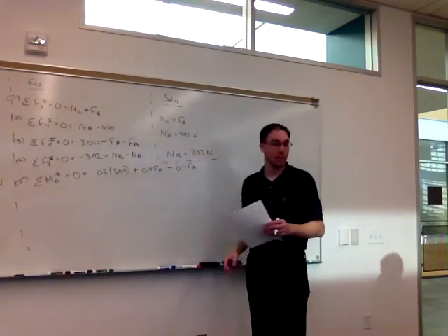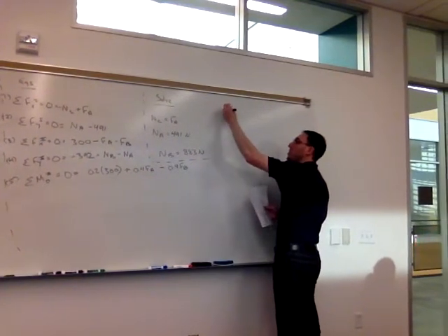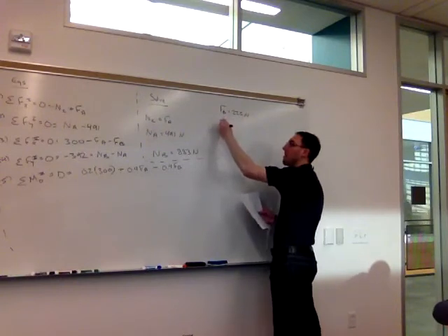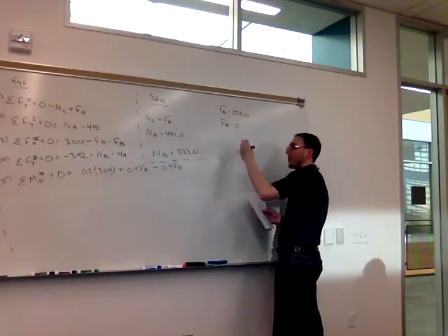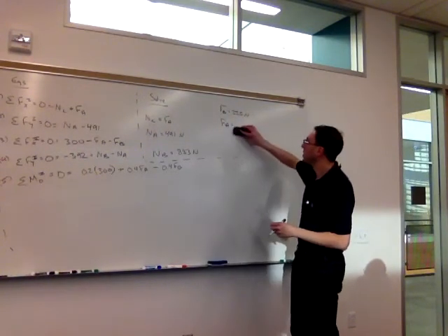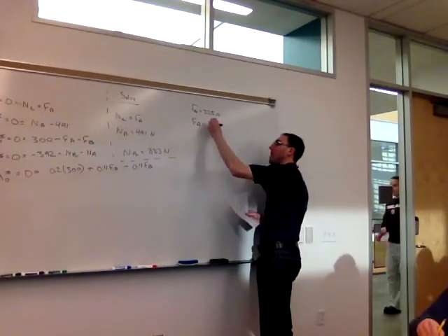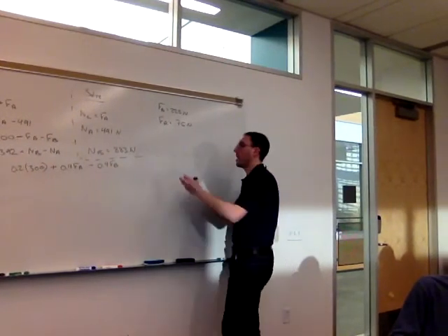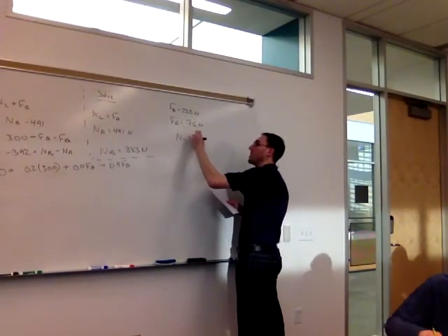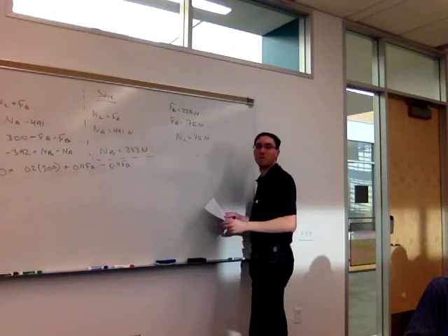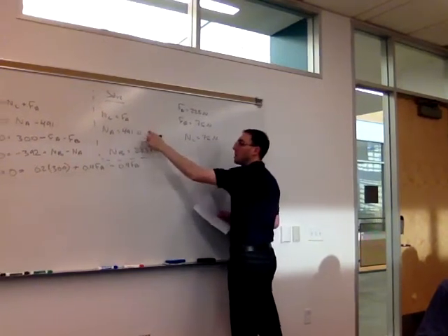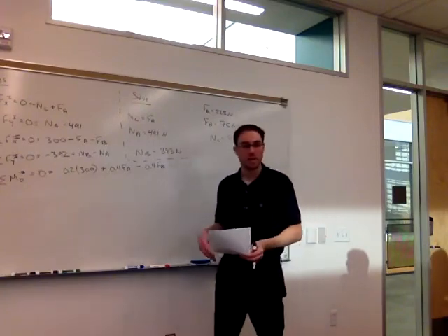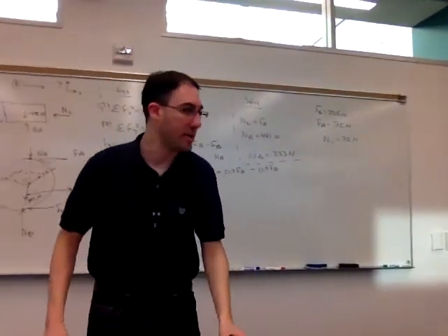Solving now this set of equilibrium equations, it does actually turn out that I get the opposite sign for FA, but that's not necessarily going to always be the case. Under this, I get FA as a positive 75 newtons. And again, NC is also 75 newtons. My 3 normal forces are positive, and my 2 friction forces are positive. So this is at least a feasible situation to have.